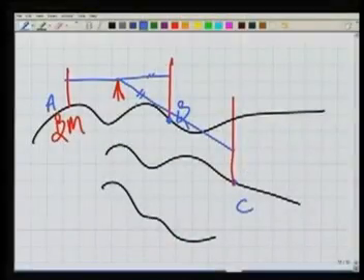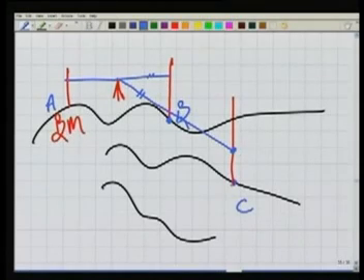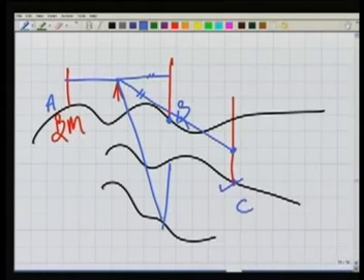Now if I rotate my level in the horizontal plane, the line of sight will sweep out a horizontal plane, wherever I am looking. Because of that, this is horizontal, this is also horizontal. So by doing that, I can determine the RL of this point also. Similarly, any other point, I can determine the RL here also. Let's say this one D, and so on.